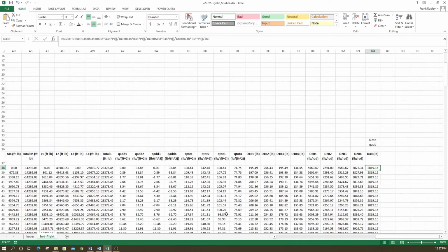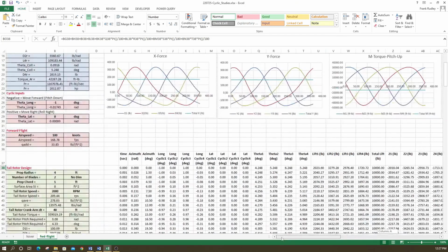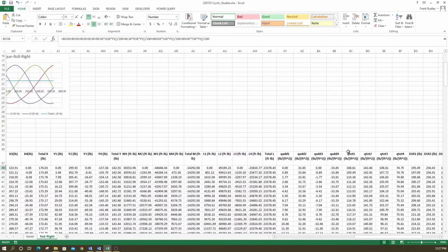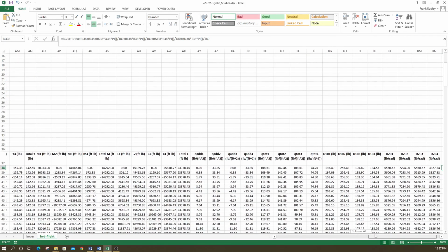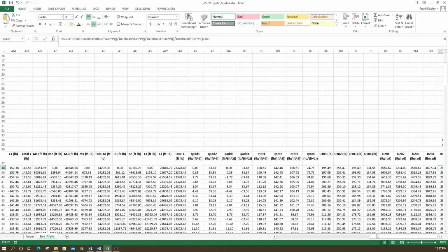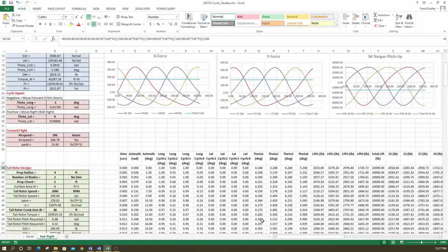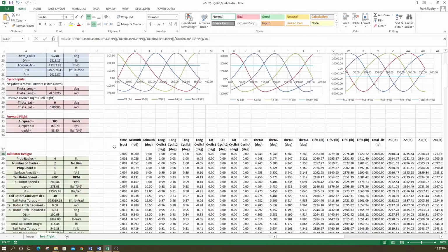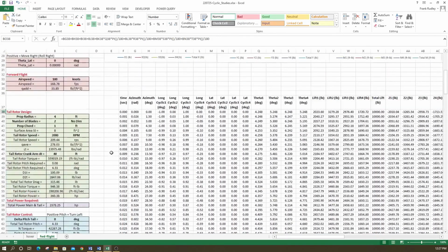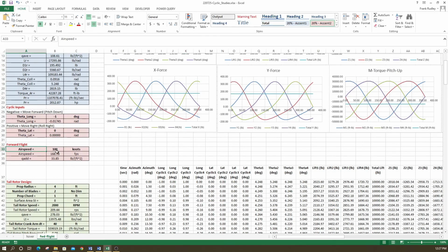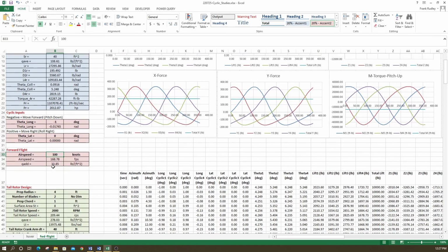Now for forward flight, I also did an analysis where I used the total Q, and what I saw was the drag. The overall drag all cancels out on the main rotor. So like here I had 218.95. It's a constant, although for all the blades it varies all over. But this was an example, say at 100 knots. I believe, yeah, see, this is my forward flight over here. So I added some columns here to add in this Q add that I showed on the equations.